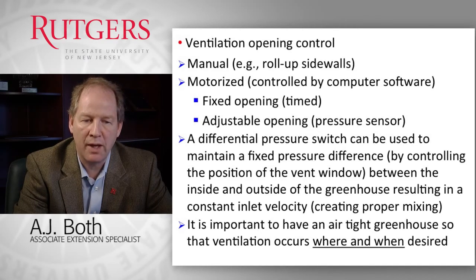We can also motorize ventilation openings, and typically that means that a computer system is involved that directs the motor to open or close the window. We can do this by a fixed opening. In other words, as soon as the fan comes on, at a certain stage the motor brings the window to a certain fixed opening, or we can have an adjustable opening